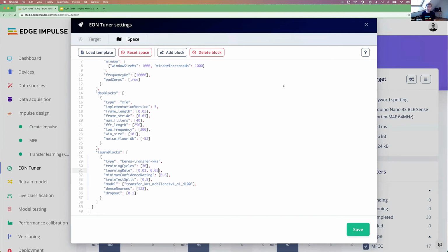You could use edge devices such as the Raspberry Pi or Jetson Nano, but that's a bit outside the scope of MCUs. One of the reasons is that TensorFlow Lite Micro does not support RNN at the moment, and we rely on that for compiling our model on microcontrollers.